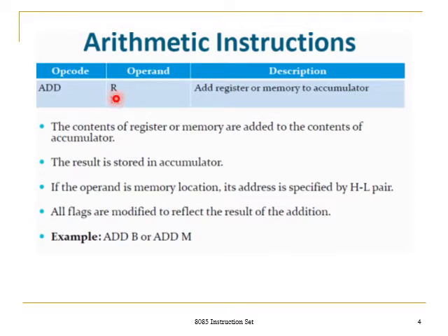While discussing the arithmetic and logic unit in the architecture of 8085, I told that the arithmetic and logic unit takes care of all the arithmetic and logical operations, and one input for the ALU comes from the general purpose registers B, C, D, E, and HL. So for any arithmetic or logical operation, one data comes from a register or memory, and the other data is from the accumulator.